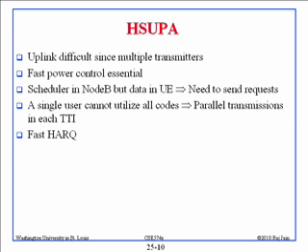So what is required is power control. Power control means everybody's level has to be set so that all are speaking at the same level. So what we have to do is listen to the user's level and say, look, you have to increase your level by a factor of 4. You have to reduce your level by a factor of 2. So there is a feedback.